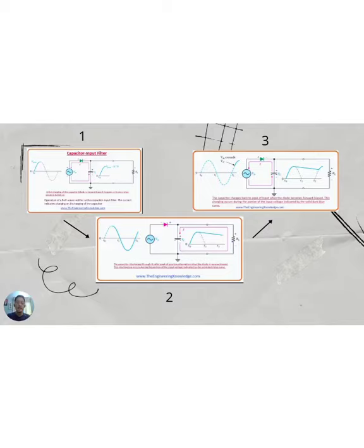In figure 3, the first quarter portion of the next cycle of the input signal is shown. The diode is forward biased when the value of the input voltage is larger than the voltage stored in the capacitor by almost 0.7 volt.